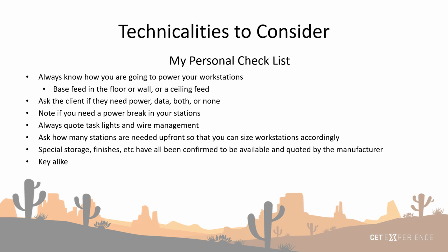And always ask how many stations are needed up front so that you can size your workstations accordingly. You don't want to develop these large, beautiful workstations for this gorgeous open space just to find out that you need to make them smaller or downsize or replan something because you didn't get that information up front. So if you're working with a large floor plate, make sure to get that information from the get-go. Also, when you get close towards the end, if you have special storage or finishes, make sure that all of that has been confirmed, that it's available by the vendor, and that it's been quoted by them as well.